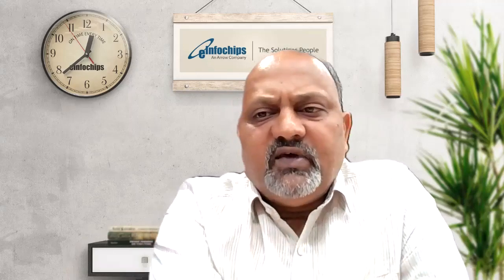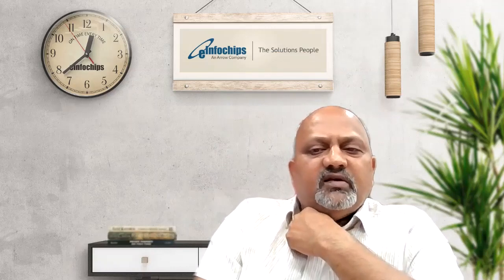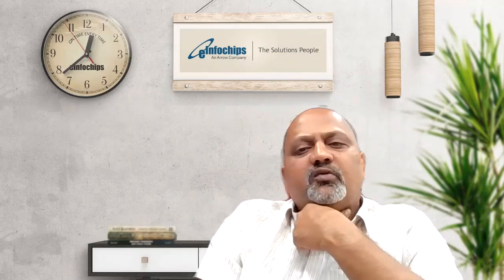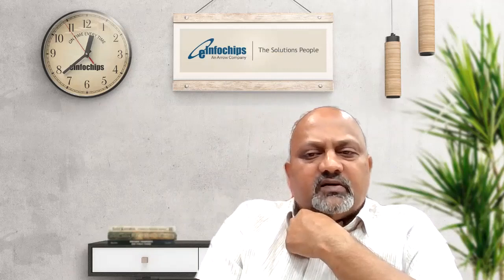Moving to the next question. How to set the fractional number of bits, f equal to 5? Here we use 16 bits. Is it fixed or can we change it? The fractional number of bits is set based on reserving the bits for the integers, as I mentioned. Take logarithm base 2 of 2 times the effective peak value, and then you can compute the fractional number of bits.